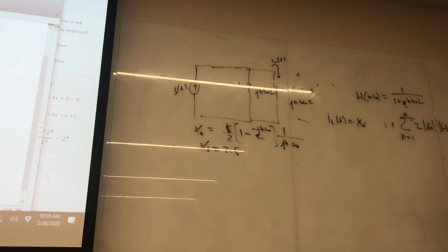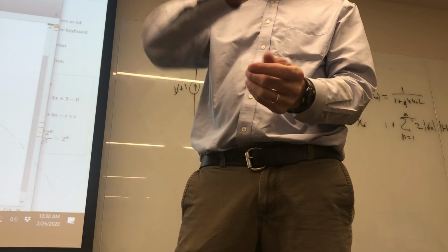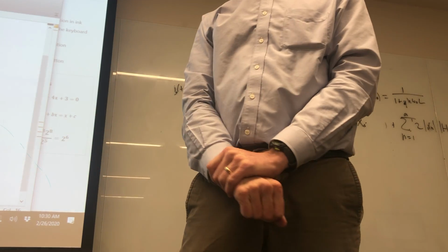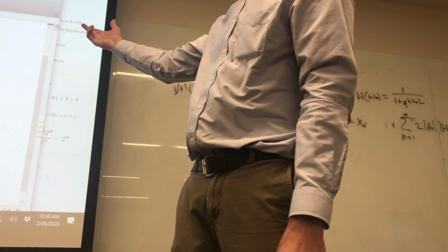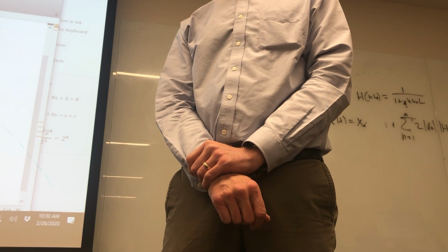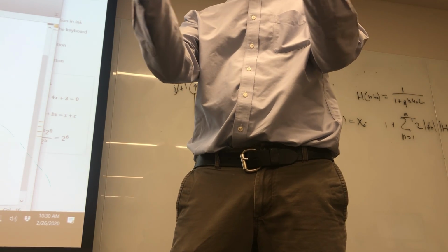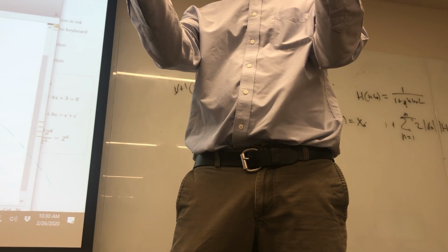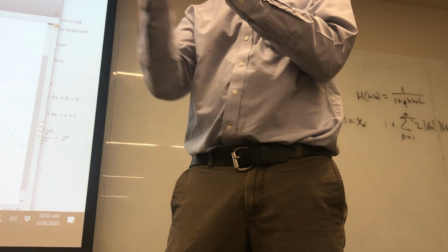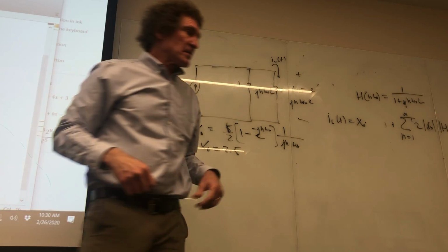All right, last thing. Any other questions about MATLAB at all? If I asked, and this is a question you're going to get, if I changed this from a square wave to a triangle, and I want the output, instead of maybe an RL circuit, like the one I have, suppose I have an RC circuit. The only difference is the transfer function, right? You could change the period. I could change tau, but fundamentally you have the structure to do any of that. Tau and all that stuff I put at the top, I don't even show it here.